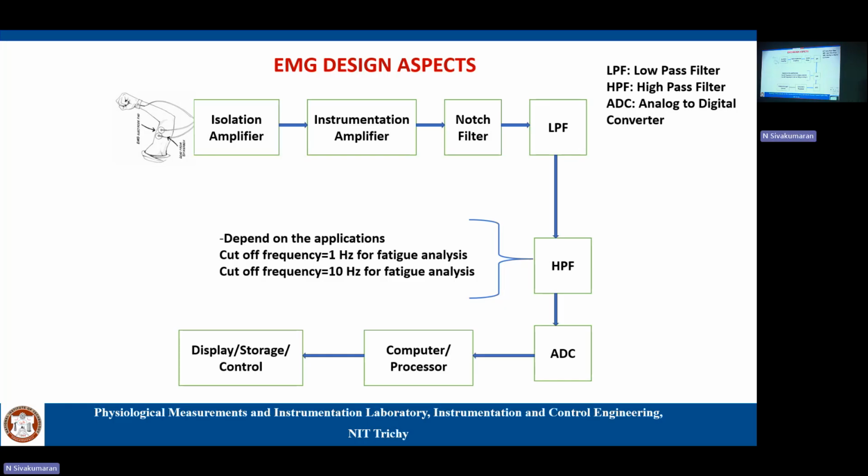When I record, 500 hertz means the useful information we will get from EMG is up to 500 hertz. The frequencies above 500 are considered noise, or unreliable information, so generally we will ignore that. So when I design, first I have my anti-aliasing filter, and what could be the frequency range of the anti-aliasing filter? If my desired frequency is 500 hertz, minimum frequency